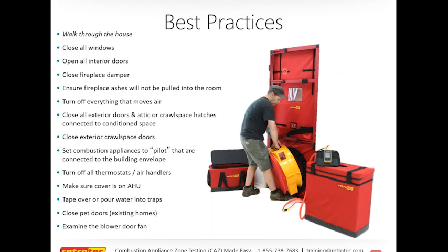So Neil says, "Do you do duct blasting?" Do I? Absolutely. I mean, I work for a blower door company that makes duct testers. Yeah, you made me say it, Neil. Good job. But that test setup is different. That's going to be with reference to the outside, but with the house open. So please, people, don't get confused.